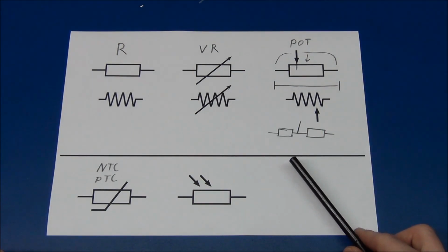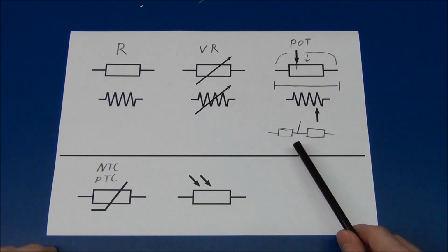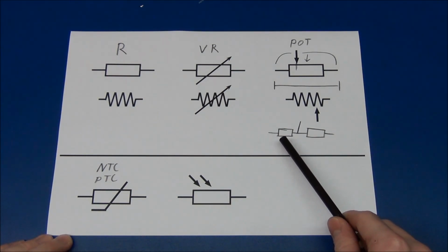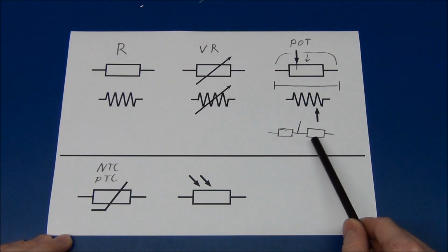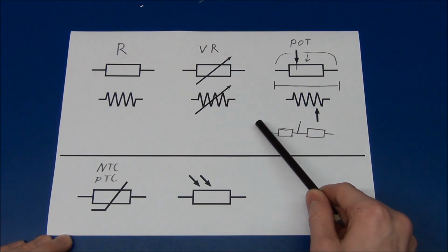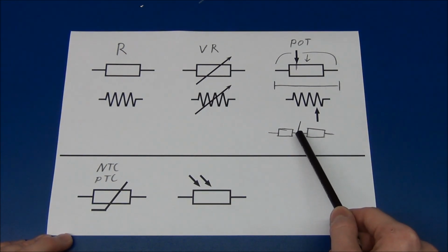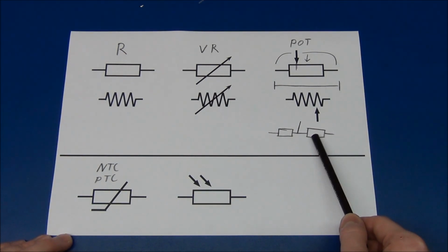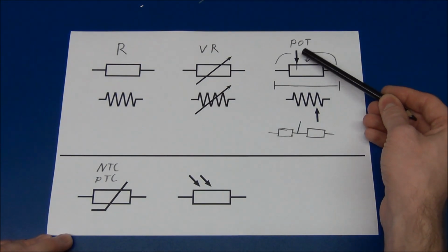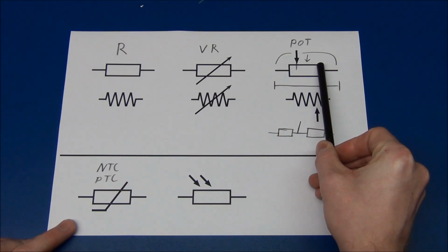And if we go back to the voltage drop we talked about before, you might remember I said that the voltage drop is dependent on the ratio of these resistors. So all the voltage will be dropped across both resistors, and in the middle we will have a voltage that is dependent on the ratio. And with a potentiometer we can set this ratio, as I explained before.